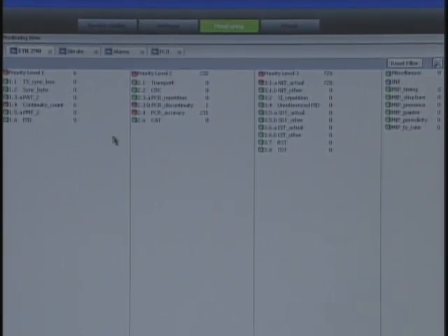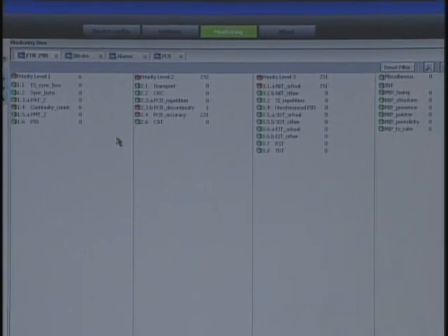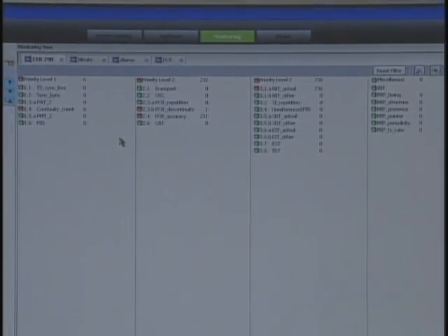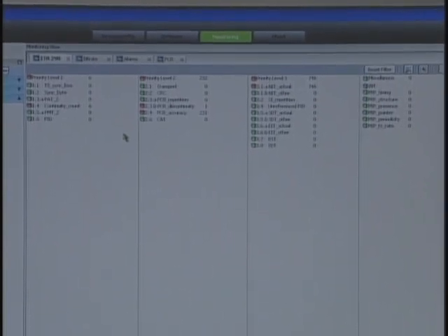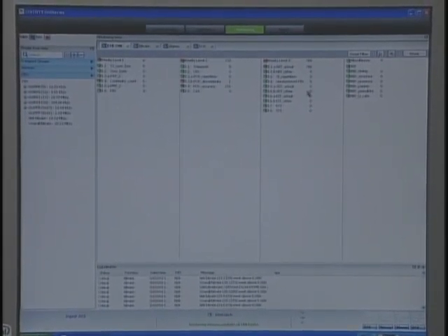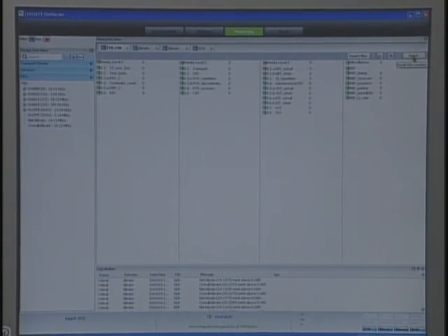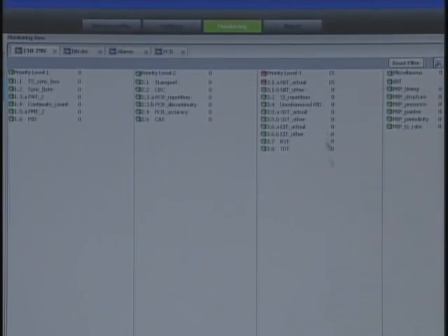You'll see that some of the alarms are green, some are red, and if you take a look down below like in the previous menu, you'll see that it tells you what your errors are about net bit rate, etc., and how it's going over the certain threshold that you set. If you reset these, most of these might go green, so let's see, and they did. Most of them went green. There's still a couple of reds because of what's set in the previous alarms menu.